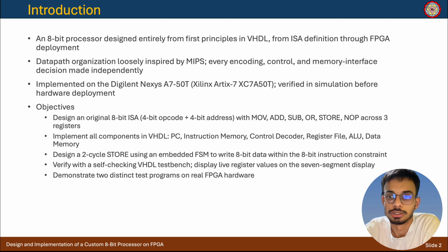The components are the PC, which stores the address of the next instruction memory, the control decoder, register file, ALU, and data memory, and it uses a 2-cycle store operation to write to memory. All the components are verified in a VHDL test bench and 7-segment display,